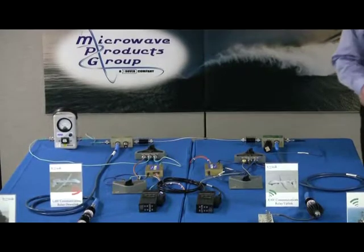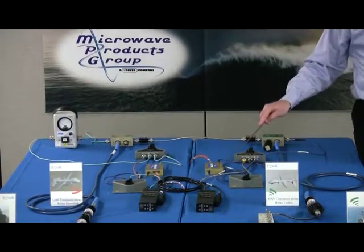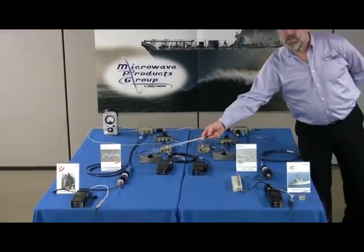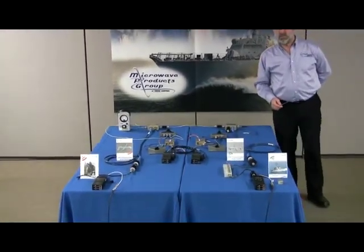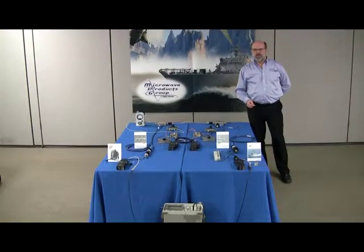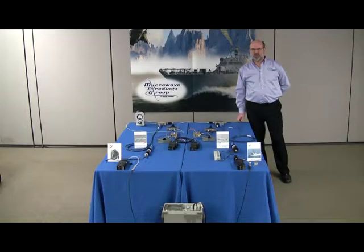Since the most vulnerable receiver in the relay is the uplink receiver, the downlink attenuation will be selected to ensure that the downlink receiver is operated 10 to 20 dB above the receiver's sensitivity to isolate the Cosite interference effects on the radio relay.